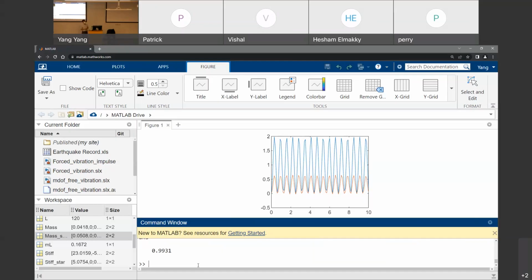The only thing you need to do is to decouple the system into a system of 2 equations, and solve the 2 equations using a numerical method, or the central difference method. That means you use your Excel to calculate the response of the 2 SDOF systems and combine them using the modal sheet.